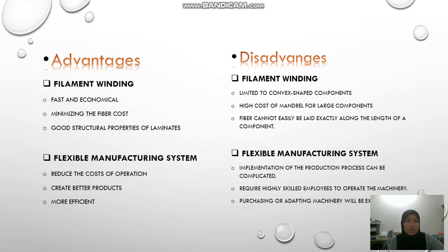And next is the disadvantage of filament winding. The process is limited to convex shaped components. And then the material cost for large components can be high, and also the fiber cannot easily be laid exactly along the length of a component.